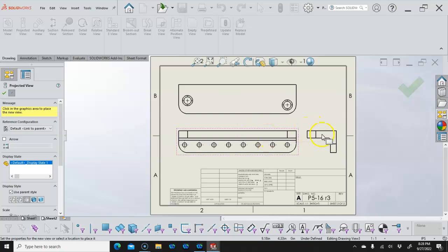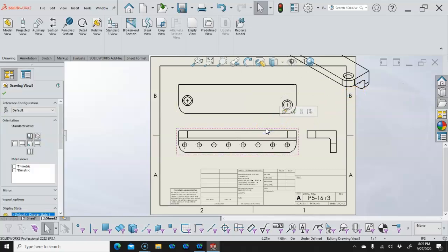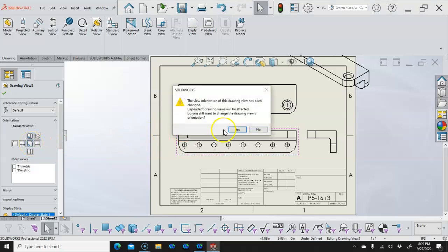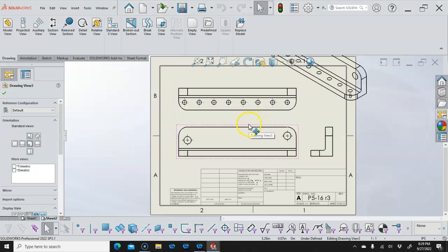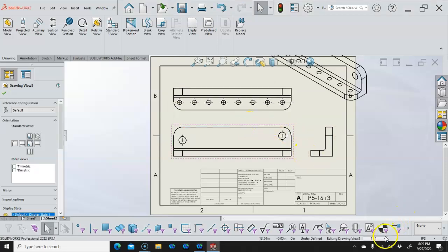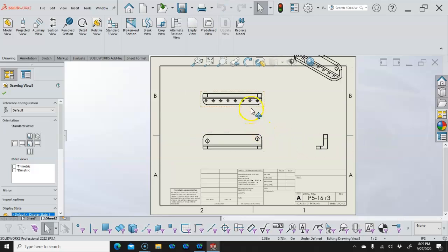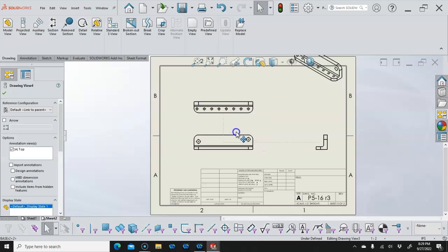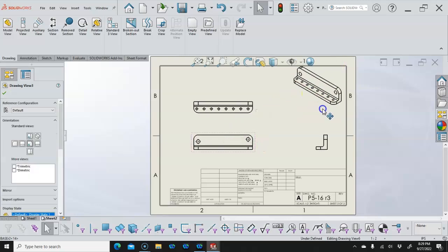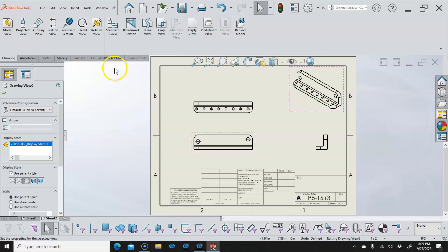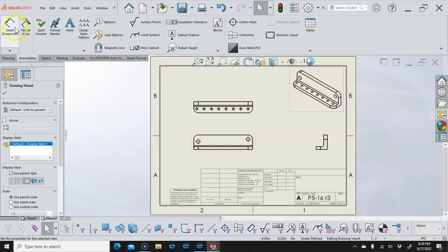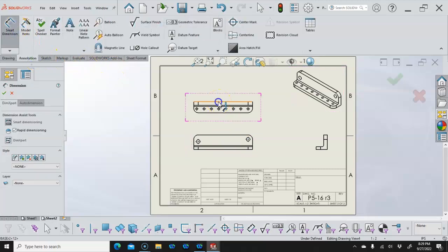why don't we go, that's going to be a little tight. We'll go with that. And I grab the top view without really looking at it. So if I jump into that, it'll take me over to the view. If I have any dimensions applied, it's basically warning me that those are going to be gone. And if we go to half size, then I can position those a little bit better. And for this drawing, we'll go to annotation, smart dimension. I have an overall.